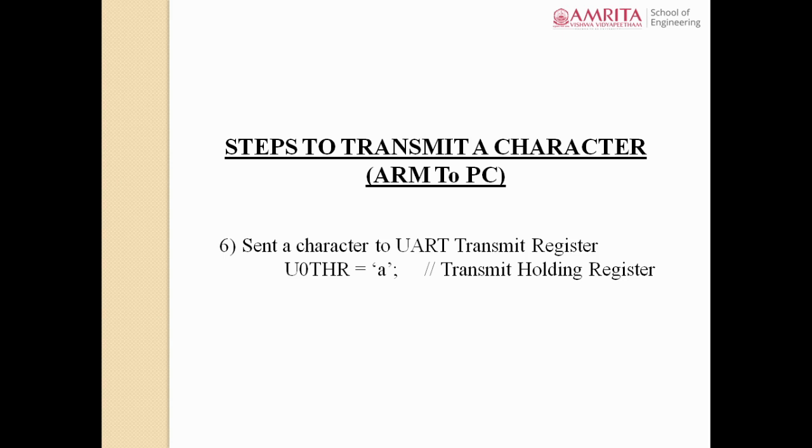How does the UART convert your data serially? So let us take you are giving a character A. How is it getting converted to serial data? So the corresponding ASCII value of a character whatever you are sending, that ASCII value will be taken by UART, right? And it will be sent to a transmit shift register present in UART.